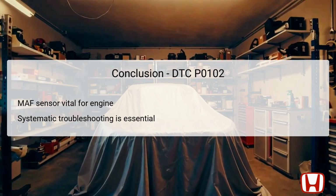In conclusion, DTC P0102 serves as an important diagnostic tool that highlights potential issues within the MAF sensor circuit. The MAF sensor is crucial for effective engine management, and understanding how it interacts with the engine control module, ECM, is essential. The systematic troubleshooting approach helps ensure that each potential point of failure is addressed, from electrical connections to sensor performance. By following the detailed steps outlined in the troubleshooting guide, technicians can effectively identify and rectify issues, promoting optimal vehicle performance.